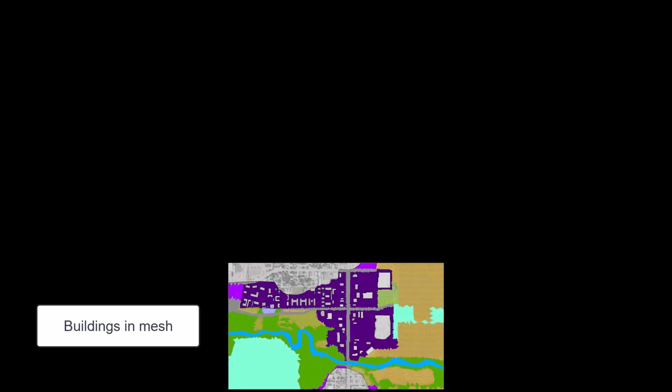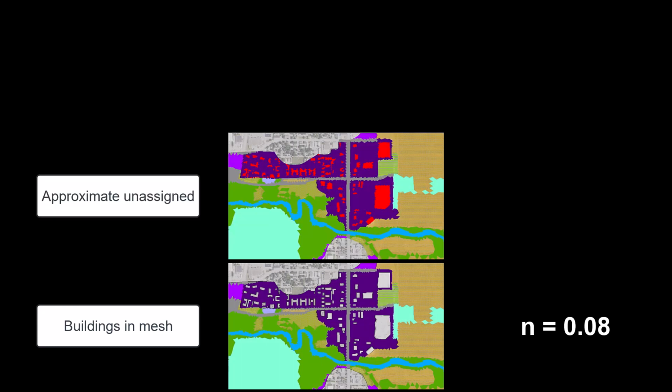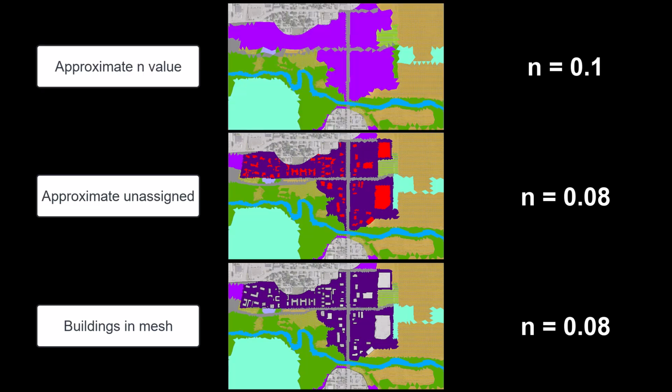For this example, using the detailed mesh as the control, with a dense urban n value of 0.08, the second approach calibrated to a similar n value of 0.08, and the first approach calibrated to an n value of 0.1. These calibrations took into account water surface elevation and flow split discharges. However, neither approach matched the detailed mesh results exactly.